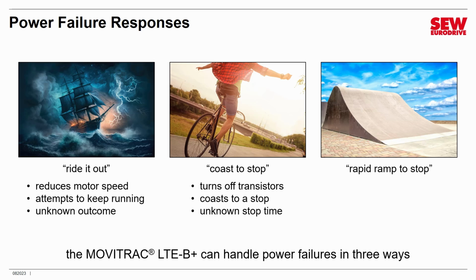Coast to a stop deliberately turns off the transistors as soon as the mains drop, and then it allows the motor to coast, and eventually it will stop. Again, though, like the other coast to stop we talked about, it's ultimately unknown how long it's going to take to stop, because that's dependent upon the load, the application, friction, and several other factors.